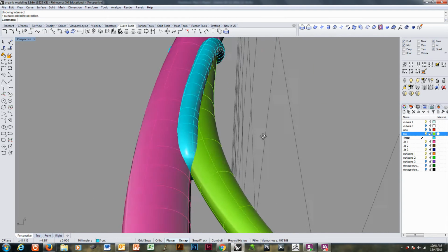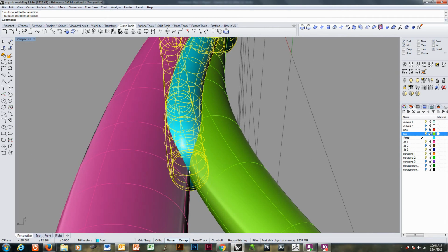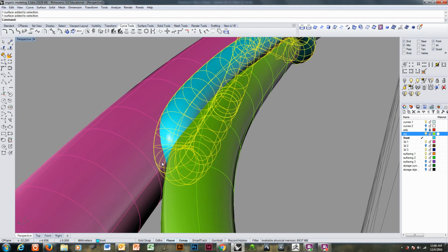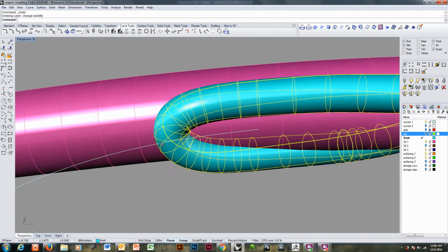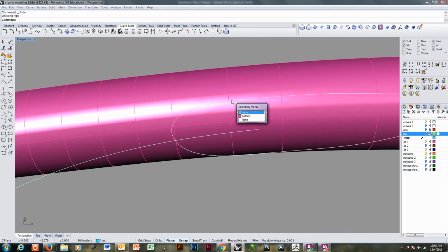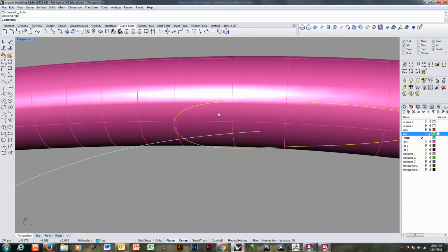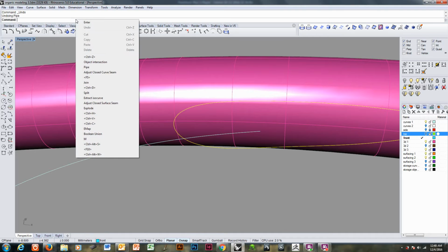Solid union. Oh, hang on a minute. This is a problem. This has to extend out enough to break through that seam right there. I'm cutting away a section that completely cuts away between both surfaces, like the cutting plane I used before to do the blend surface. I'm going to do a blend surface to make this Y seam work.